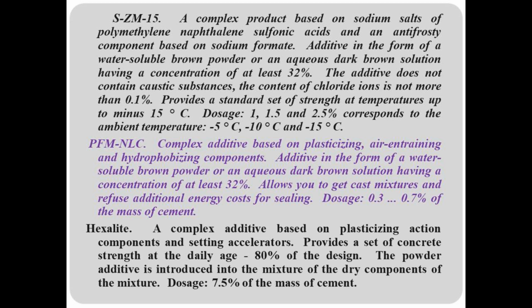Additive in the form of a water-soluble brown powder or an aqueous dark brown solution having a concentration of at least 32%. The additive does not contain caustic substances. The content of chloride ions is not more than 0.1%.